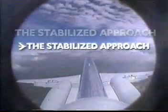The stabilized approach. When the whole approach is properly controlled, the possibility of something going wrong is drastically minimized. Avoid power-off approaches. Recall the poor acceleration response of your jet aircraft and set power with judgment. Anticipate the need for more thrust should airspeed decrease, but don't leave power up for too long or the aircraft will go fast again. Keep thrust in such a value which allows the engine to accelerate to a higher RPM if necessary. And it is also good to keep the airplane in the approach path.